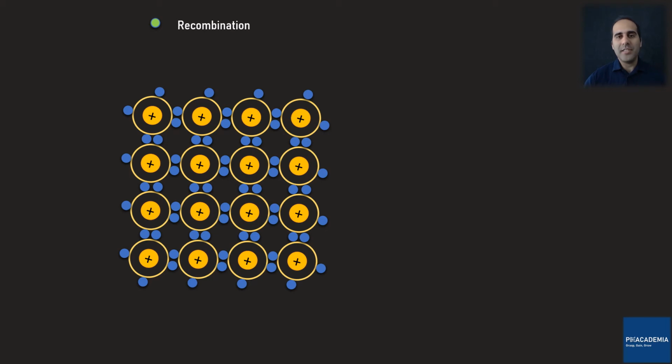Let's get back to the statement that both the electrons and holes are considered as charge carriers. Although it is crystal clear for a free electron to be considered as a charge carrier, it is not for the hole. A hole is simply a vacant site and a product of a broken covalent bond, or in other words, the generation process. This vacant site or hole does not move. So how are we considering a hole as a charge carrier if it does not move?